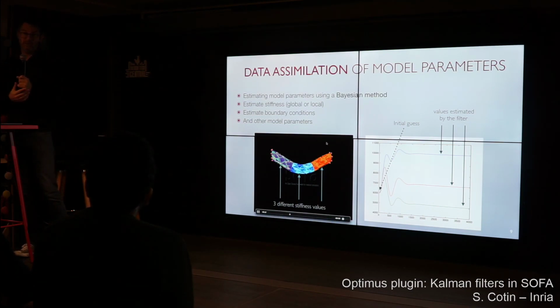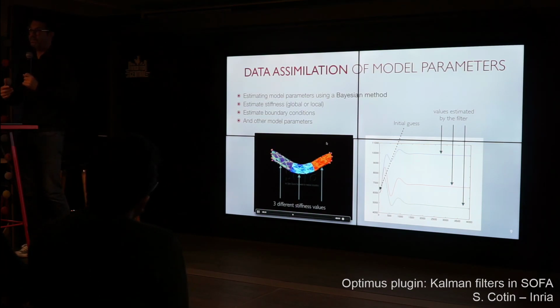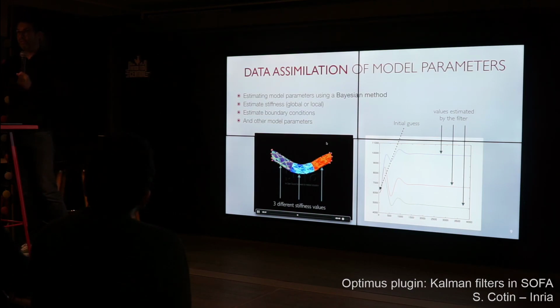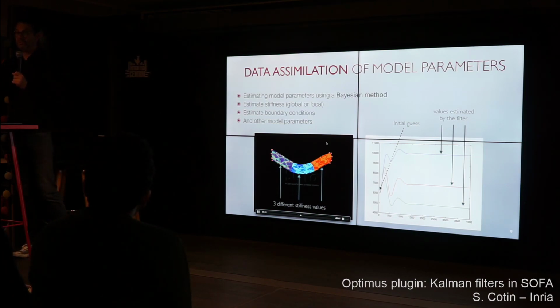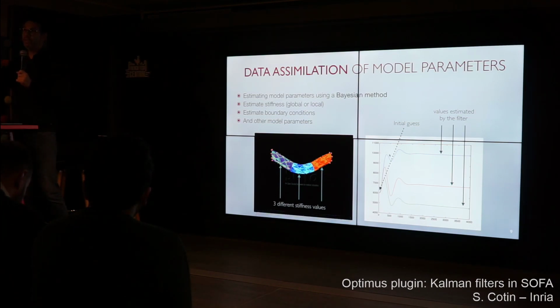They're measurement points, here in 3D. Those points have a different position in the simulation, the prediction, than in the real world. Through the difference between those two, the algorithm will modify the stiffness parameters, while maintaining them within the Gaussian distribution.